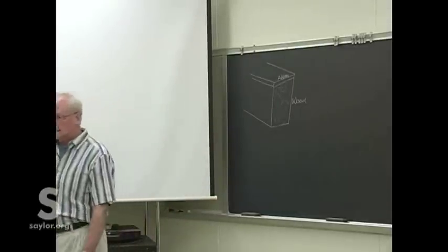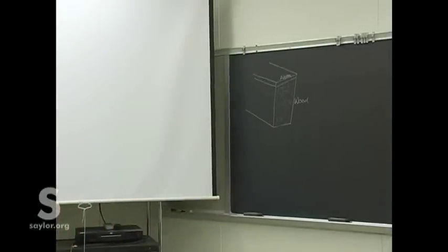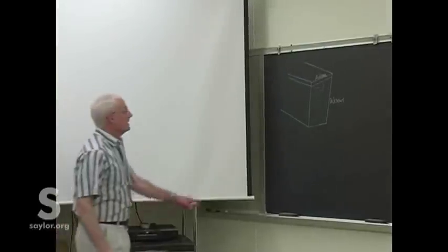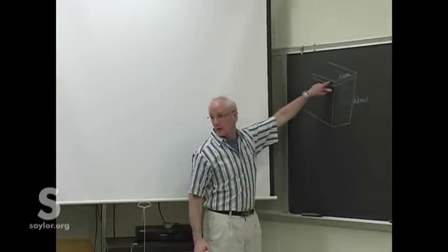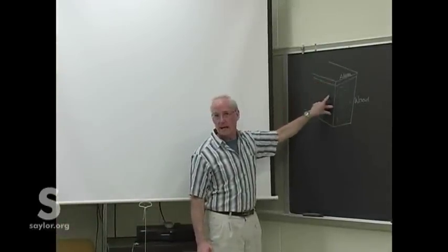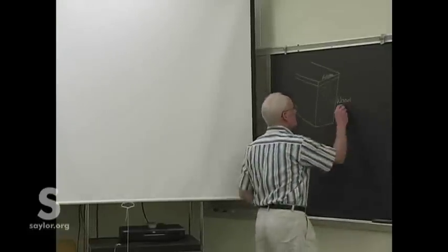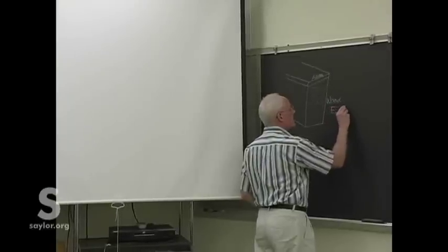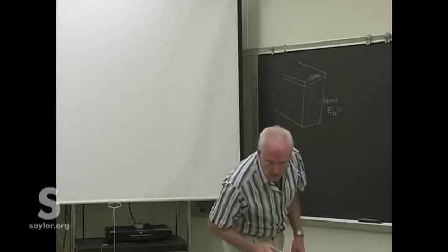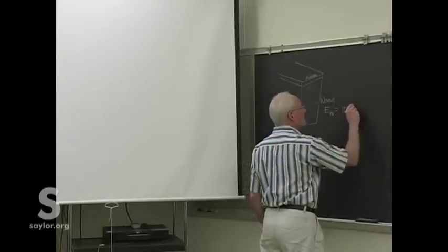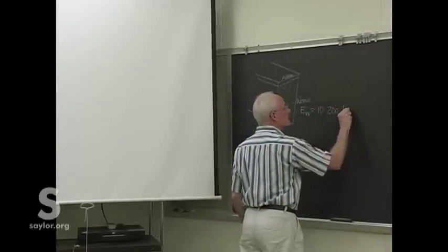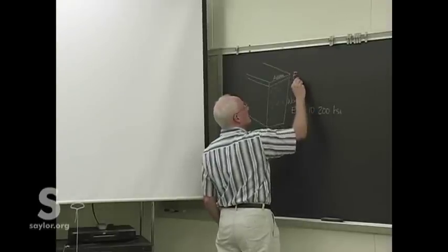If you were a structural designer for a great Adirondack camp, your customers are not going to be real happy if the beams are aluminum. They're going to be a lot happier if the beams are wood. So we'll design for that kind of wood. I mean, that kind of beam. So let's see. The Young's modulus for wood is 10,200 KSI.